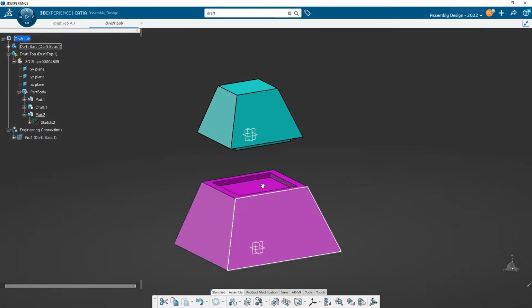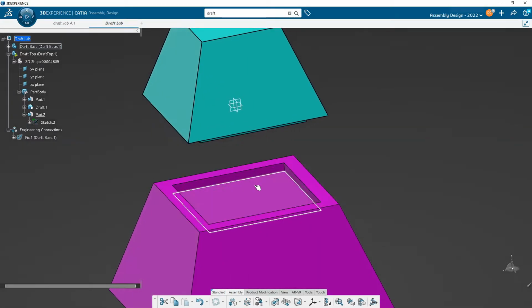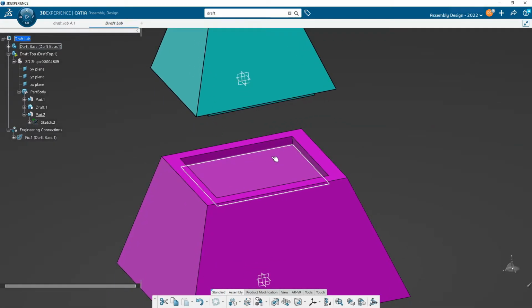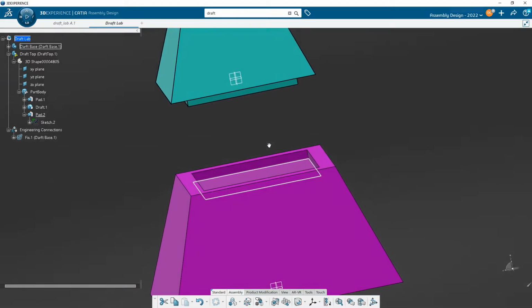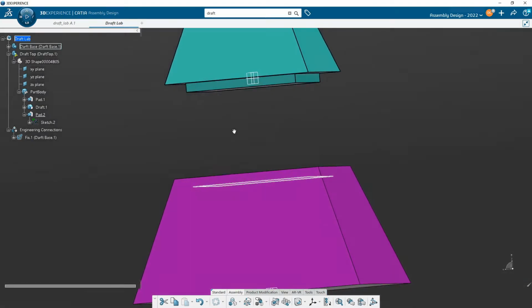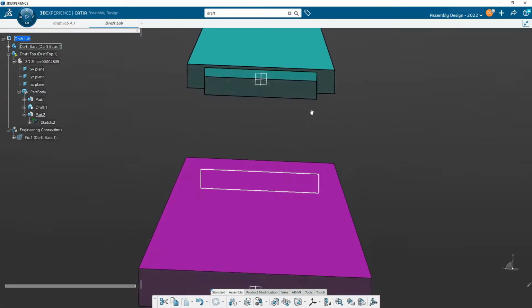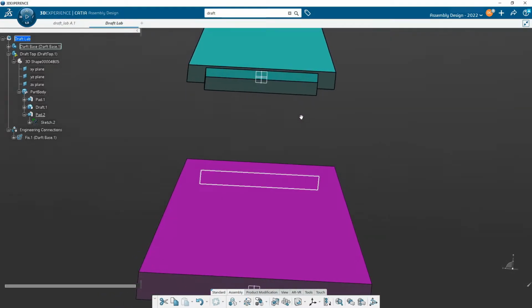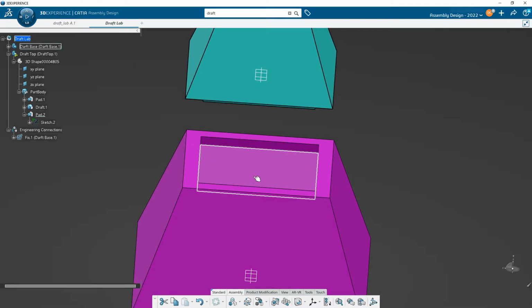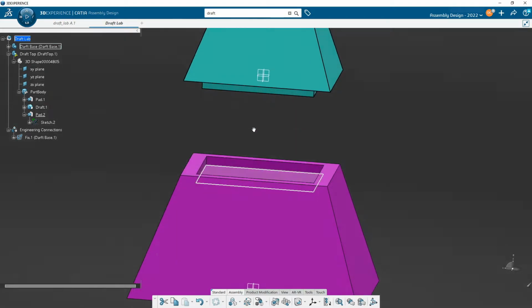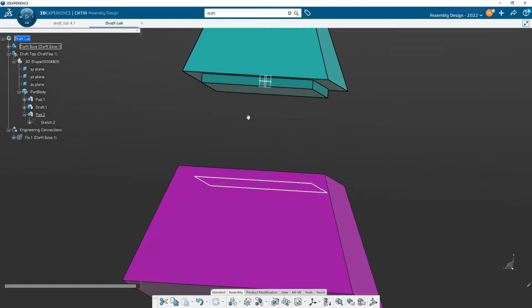Okay, so this is a topic about assembly connector points. This is not a name that you're going to find in a textbook. It's just something that we call this. So if I have two parts of an assembly and I have some way to connect them together, like this face to this face, that's great. If I happen to have a nice little point and there's a nice little cavity down here and I can match point to point, you bet, absolutely do it. But if you don't, then you make one.